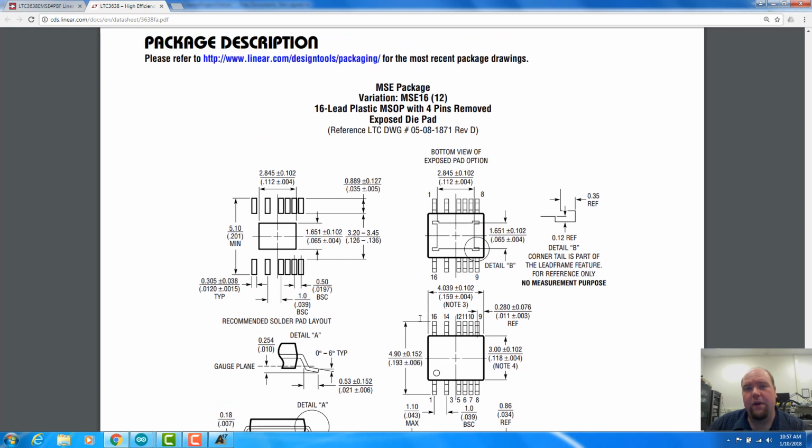The point of doing a 3D body or a physical geometry, which we'll do for this, is to make sure that things don't bump into each other. So if you have a tolerance for the part, and you use the largest possible size that's specified in the data sheet, that's going to guarantee you that if two things don't collide, they're not going to actually collide when you finally build your board. It's not such a big deal for these parts, but when you get to big capacitors and big inductors, things that really stick up off the board and get bigger than where they connect, then it becomes really important to use the largest specified geometry within tolerance.